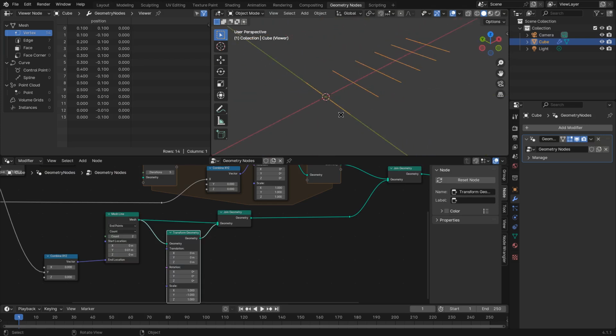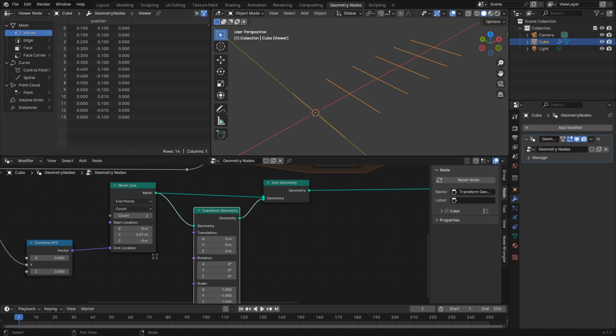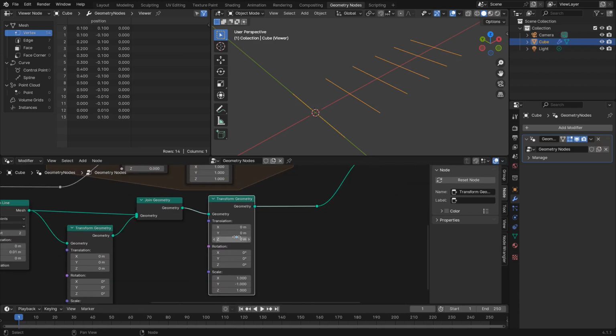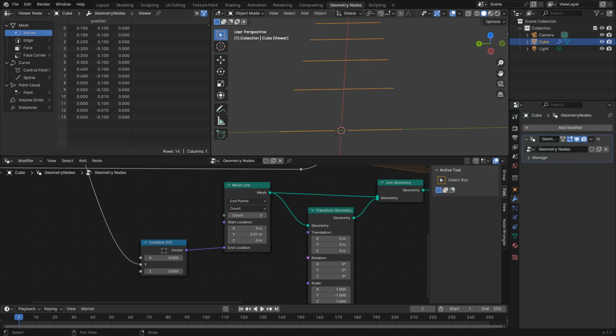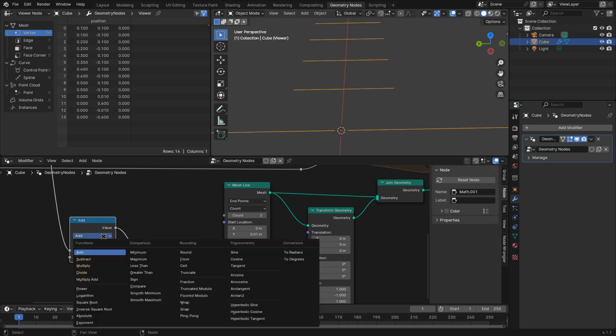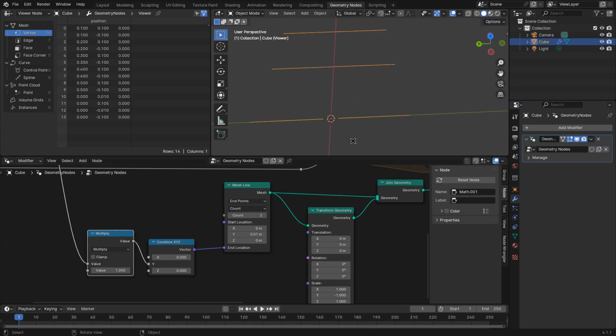So usually the driven element is slightly longer than the other elements. We could make this a parameter of the antenna. I'm just going to make it 5% larger than the other element. So let's use another transform here and scale it on the y-axis by 1.05, like this. And actually that's not what we want, because it's going to scale the port too. So let's remove it from here, and instead multiply here by 1.05, like this. And now we still should have our 0.01 start position here and 5% larger here.